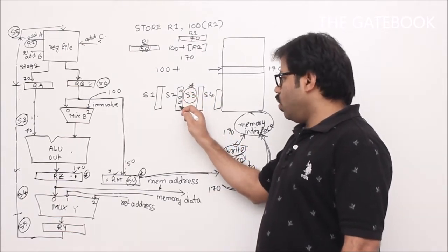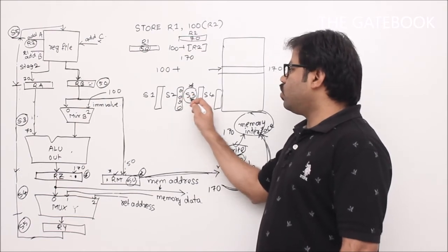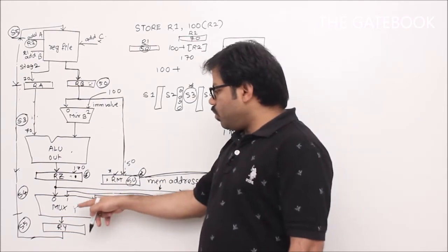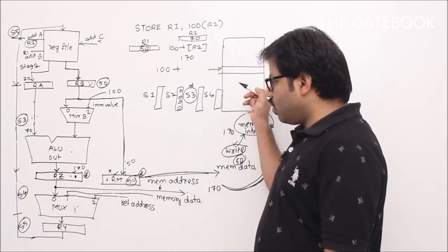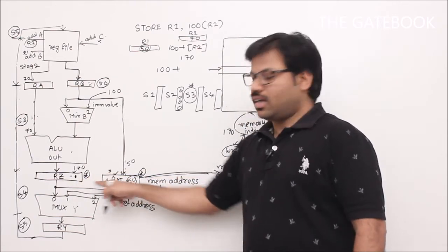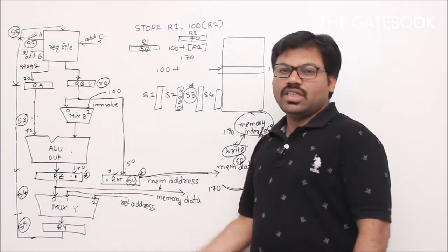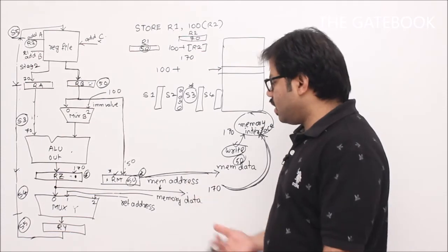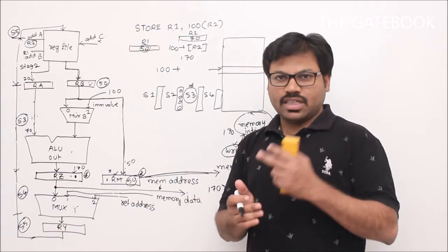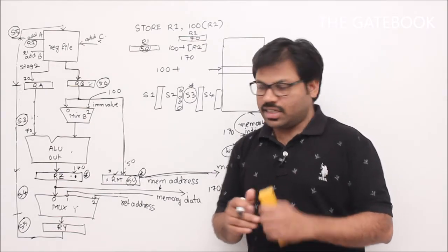That we have to hold in the registers between S2 and S3. Here also we are doing the same thing. To do the computation of storing the result into the memory, we are holding the data in the registers between the stages, correct? So that is the right thing. We will see why, because in pipelining we will be using it extensively.